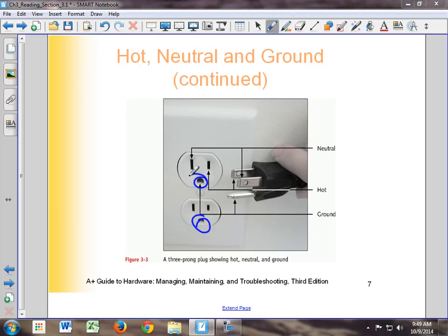Without the ground, the power supply in the PC is even more susceptible to electrical fluctuations. That third plug in your power supply goes to ground, so that your PC is always grounded. If you have electrical wiring that does not have that, or like my house has 3-prong outlets but nothing wired to that, then plugging in a 3-prong doesn't do anything, and there's no ground, which means surge protectors don't work. It means you have no grounding protection on those electrical plugs.